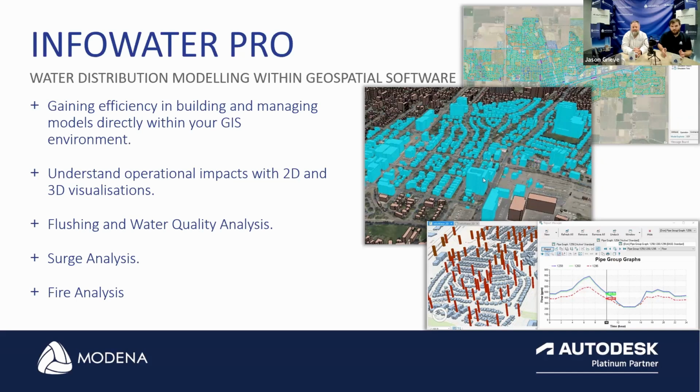To which areas is this going to propagate into? You know, we might be worried about further down the line how that is going to just increase in efficiency and multitude. And then with regards to the phi analysis, the nice thing about the phi analysis is we don't have to analyze each hydrant one by one. This actually allows us to specify the flow for all hydrants, and we can then run a simulation that runs all theoretical possibilities with all hydrants simultaneously. So it removes that need to run multiple analyses after one another and then compound that information as we do those analyses.